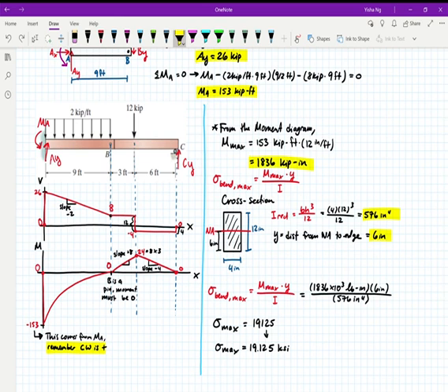And then here you've got a negative 4 shear force, which is acting for the whole rest of the beam. So I'm going to go from 24 with a slope of negative 4, all the way back down to 0. Because there's no moment acting on the end, I don't expect there to be a jump at the end. And so that's a good check: my area, negative 4 times 6, also takes me back down to 0. So it's always good to check that your moment diagram starts and ends at 0.